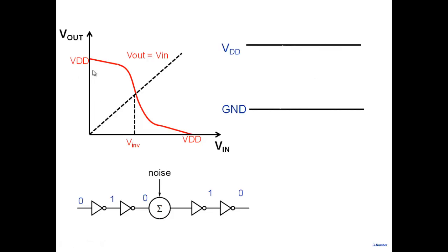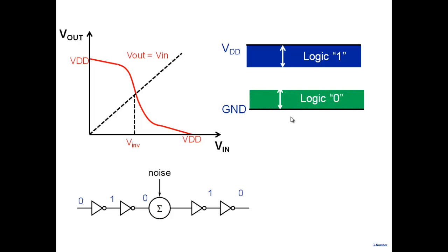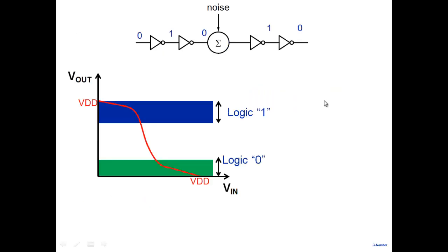So let's look at our system here. This is what we are looking for, logical correctness. Logically it should work correctly, and we have to map logical 0 and logical 1 to some levels here. So I have one level VDD and one level ground. And we know that simply calling these logic 1 and logic 0 makes no sense here. Maybe what I should call logic 1 is a band of voltages and another band logic 0. Anything which lies within this will be interpreted as logic 0. Anything which lies within this will be interpreted as logic 1. Now the issue is how large: how far should I dip in and how far should this go up, and still I can call it logic 1 and logic 0. Okay? So let's come back.